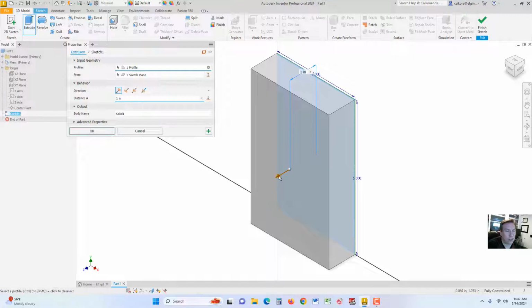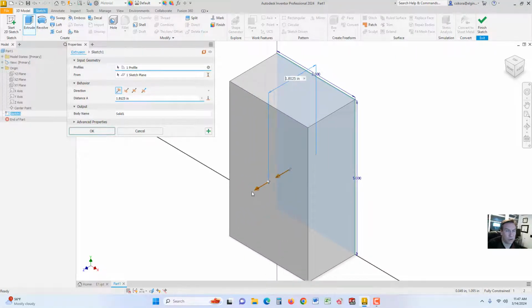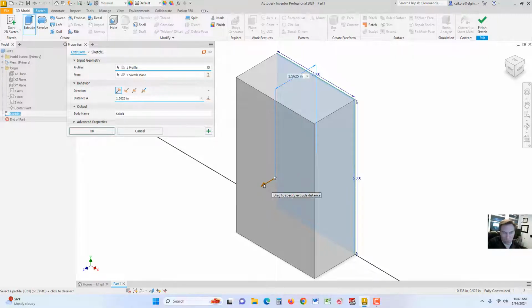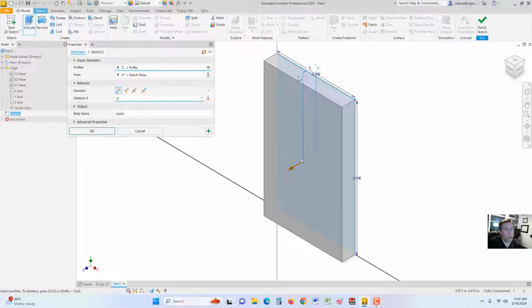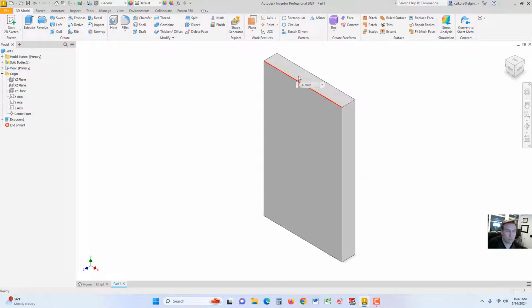All right, and here you'll see for conceptualization work, you have the ability to grab this arrow and drag it forwards or backwards. Make sure it's pulled forward. Now, you'll see the dimensional constraint is up there. Let's go ahead and put in 0.5. Now notice I didn't click in there and backspace on it. That's another bad habit. Makes you look inefficient if you use that. I don't really care for my students if you do or not, but if you ever get tested for a job during an interview and how you use the software, never do that because they're going to sit there waiting like, oh goodness, this is a novice user. Whereas it makes you look much more advanced if you just type in what you have there. So 0.5, I hit enter. Okay, so now we have our first solid model.